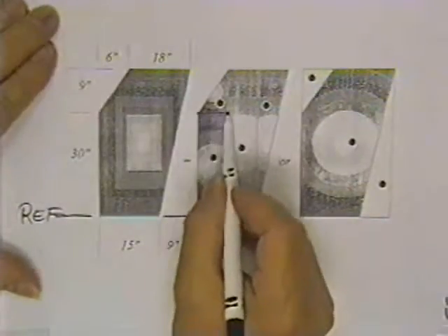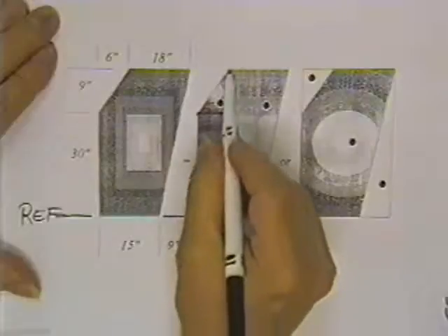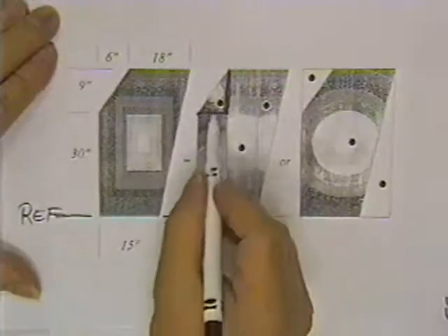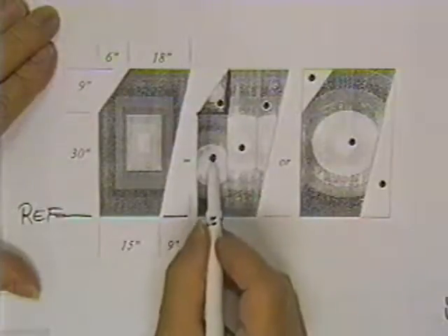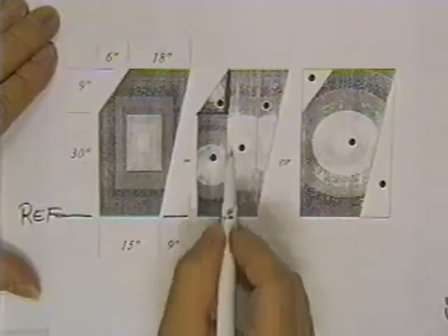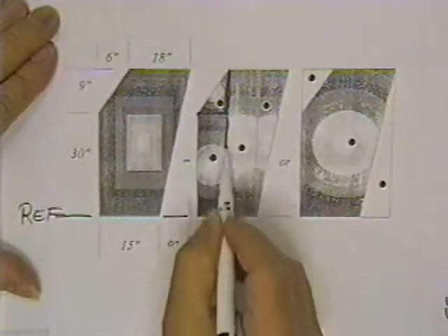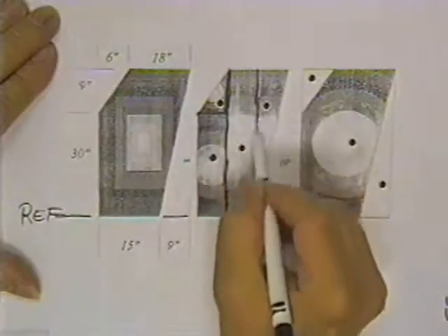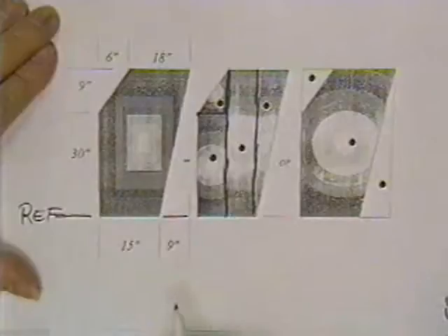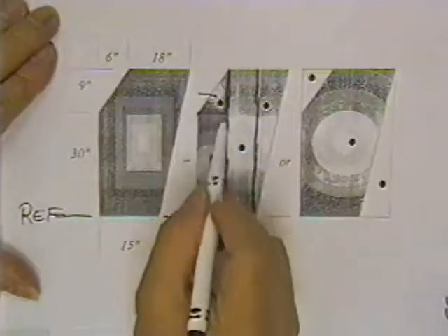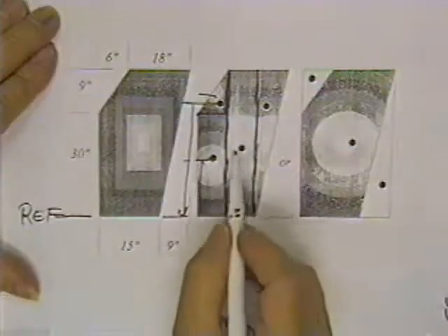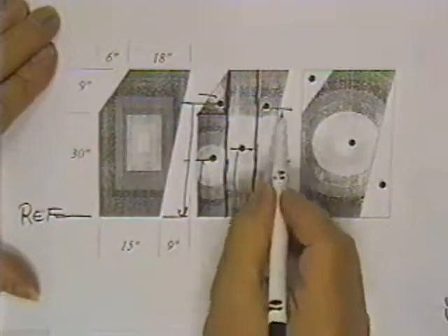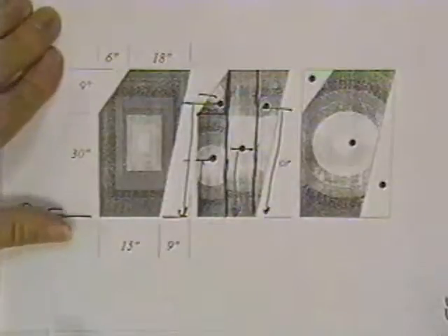Here's one way you could split it up. You could split this up into a triangle, because I fully know the area of the triangle, and I know its centroid is 1/3 of the way up. That would leave me a rectangle here, and I know its area and I know its centroid. I could leave this rectangle up here alone, and then finally I'd have another triangle with those centroids. I could say area 1 times distance 1 plus area 2 times y2 plus area 3 times y3 plus area 4 times y4, and I have the answer.